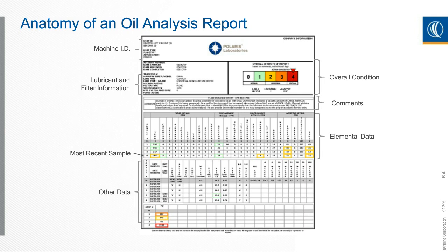You always want some kind of reference point. So one of the most important parts of an oil analysis program is to always have baseline samples identified on each report. You want to look for hours of oil in service, hours of the filter, any top-up information. It's good to show trend graphs. Sometimes that's on the second or third page. Look for any data patterns.